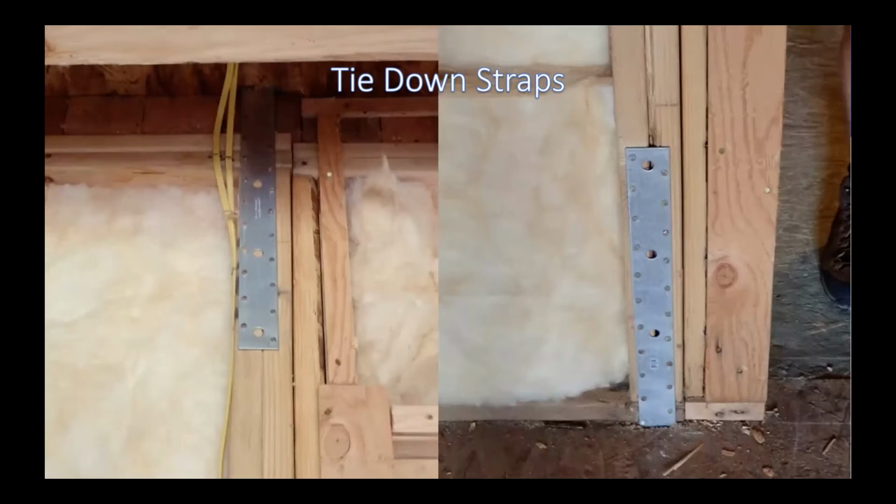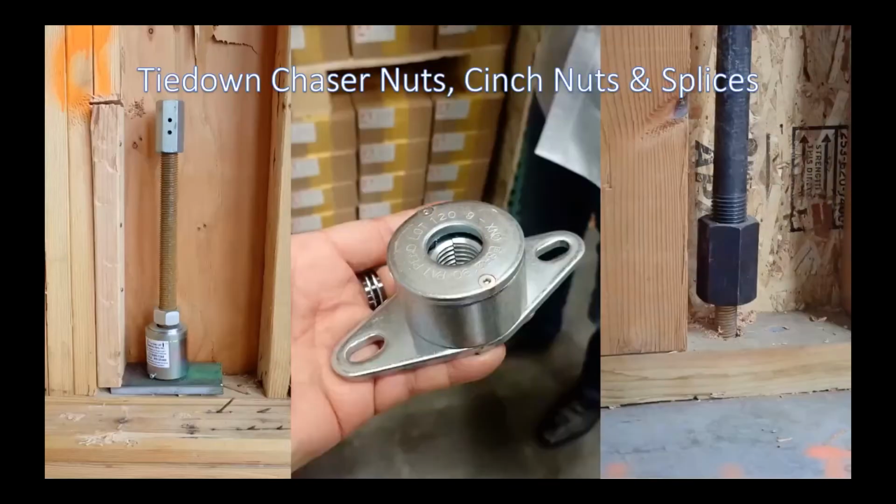There's a lot of tie-down straps like these being used, and there are a lot of full-length rods that tie right from the concrete podium or concrete slab below right up to the very top of the roof, with spliced rods that go up to about 3 inches. I've seen 3 inch rod being used over there, 75 mil rods, huge rods, down to small rods like this, 16 or 20 mil. And they have different systems for splicing, like the nuts on the right to splice.